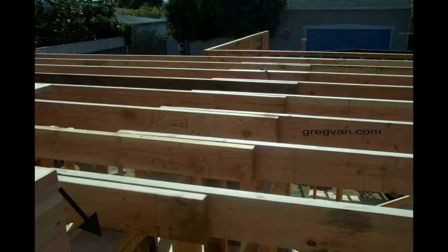However, if you run across something like this, where the ceiling joists lap over a wall, you can see that the end of the ceiling joists on the right and the end of the ceiling joists on the left are actually sitting on top of this wall. There would be a good chance that this would be considered a structural load-bearing wall and would not be able to be removed without some type of structural engineering and redesigning of the structure.